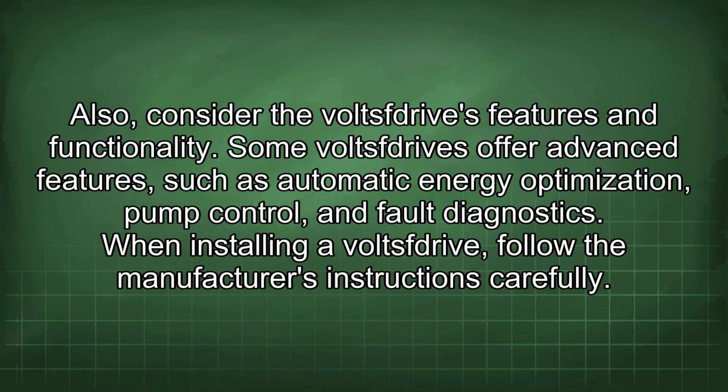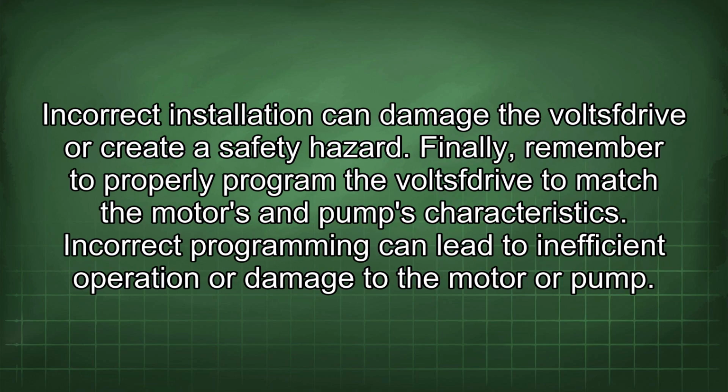When installing a VFD, follow the manufacturer's instructions carefully. Incorrect installation can damage the VFD or create a safety hazard. Finally, remember to properly program the VFD to match the motor's and pump's characteristics. Incorrect programming can lead to inefficient operation or damage to the motor or pump.